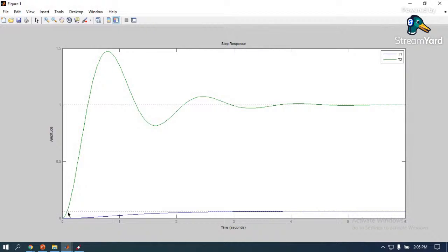So if I use the PID controller and find the exact values of Kp, Ki and Kd, then you can see at the end, as you have introduced the integral controller, obviously you will get error as 0. Final value and reference value will always be the same. But it will require certain time. See, it takes 3.9 seconds. Right? Now just tell me, is T1 best or T2 best?